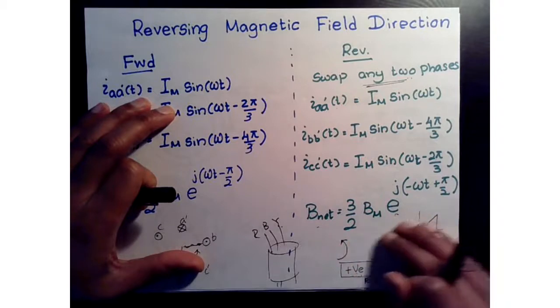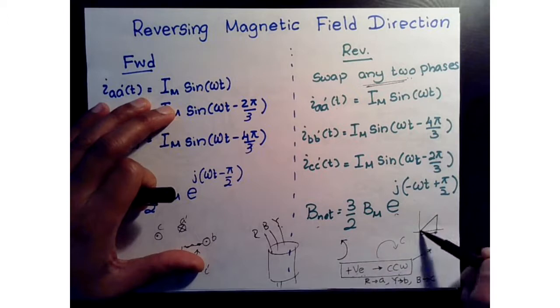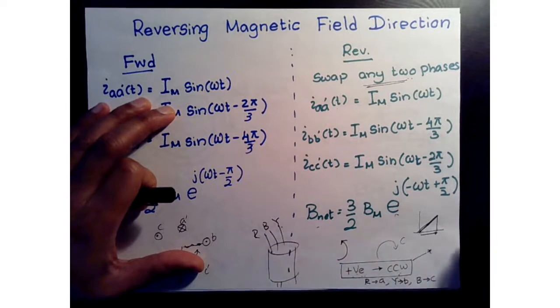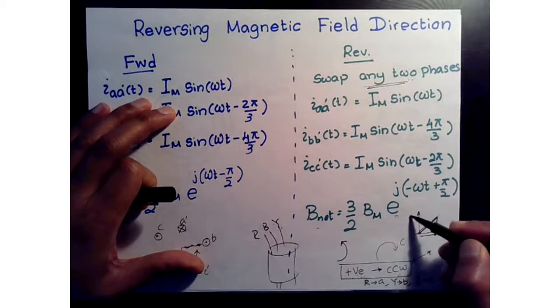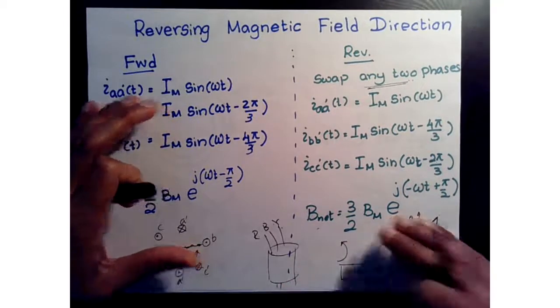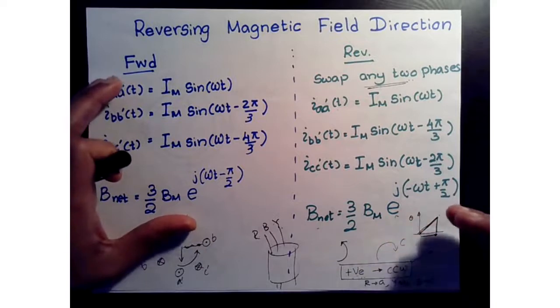If you don't have any data sheet or information on that, you can choose what your positive slope is and what phase sequence gets you to rotate in that selected positive direction. It could be clockwise that gives you this positive slope, or it could be counterclockwise. So it's important how the windings and the currents relate to get you to that direction of interest.